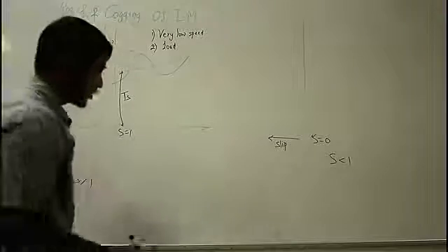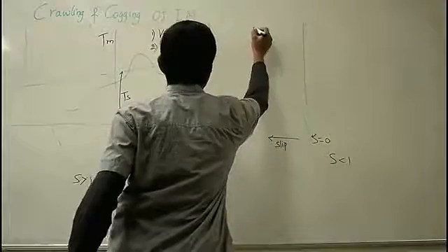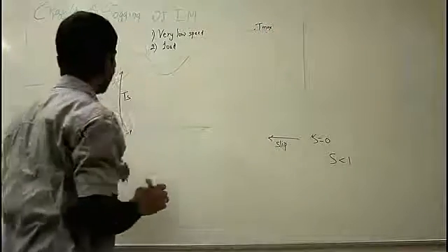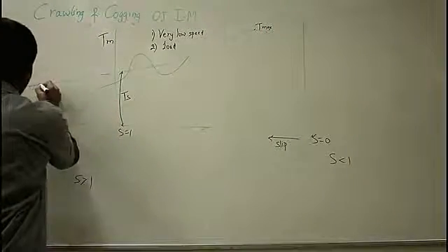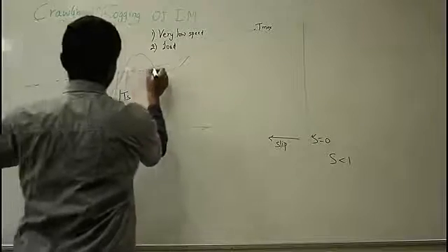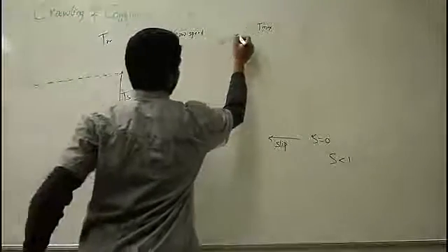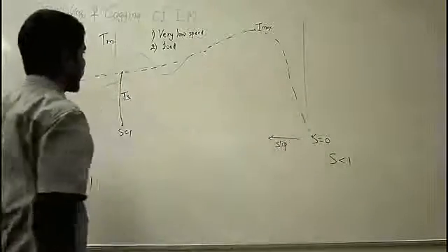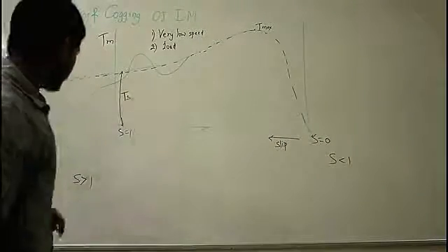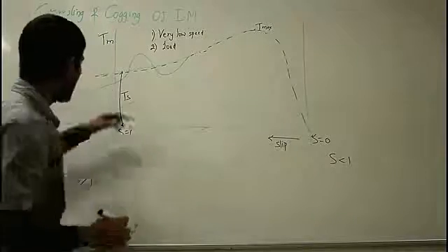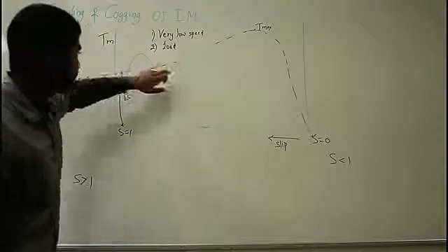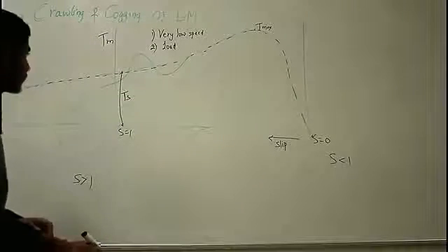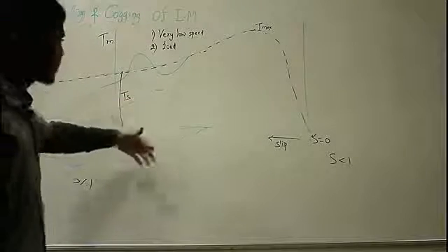Now in the torque slip characteristics, here you have T maximum, and this is the normal torque slip characteristics shown by the squirrel cage type of induction motor, and these are the harmonics. This characteristic is due to the harmonics produced by the stator winding. Now we shall discuss this. What are the harmonics here?